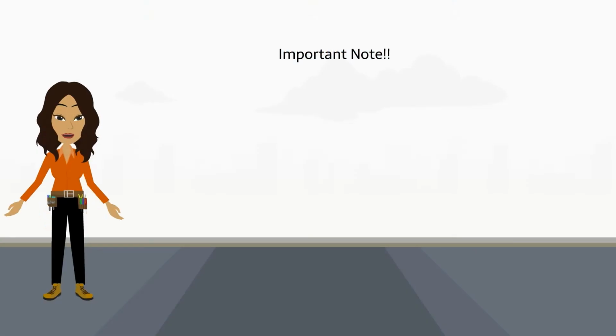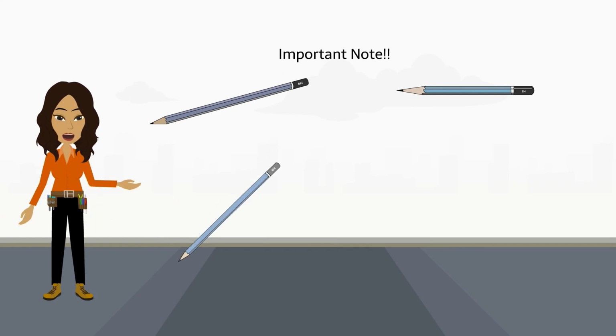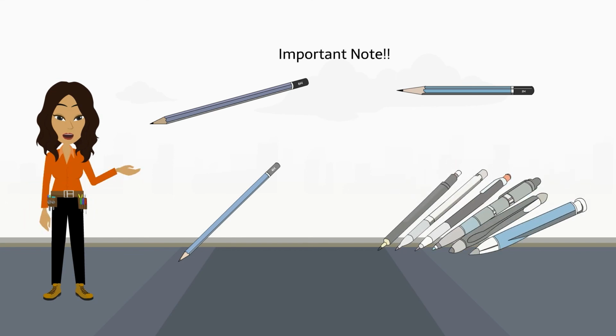Important note: consider a 2H pencil for most lines of finished, darkened drawing, 6H for construction preliminary work, and 4H for center, hidden, and dimension lines. All finished lines are to be black. Also, consider metric lead and metric lead holders, 3 mm, 5 mm, and 7 mm, to avoid sharpening a pencil so often.